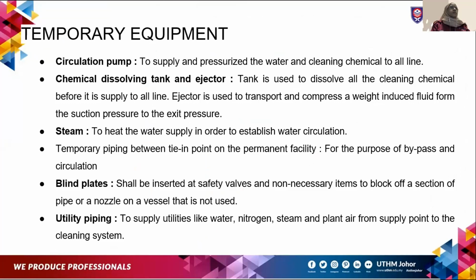Okay, so I'm presenting next the equipment that is necessary. First, a circulation pump. The circulation pump is used to supply and pressurize the water and cleaning chemical. Then the dissolving tank and ejector. The tank itself is used to dissolve all the cleaning chemicals and also mix the chemicals before they are supplied to all the lines, while the ejector is used to transport and compress an induced fluid from the suction pressure to the exit pressure. Next, we use steam.